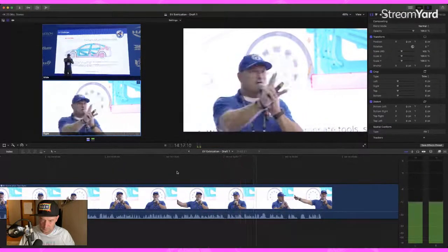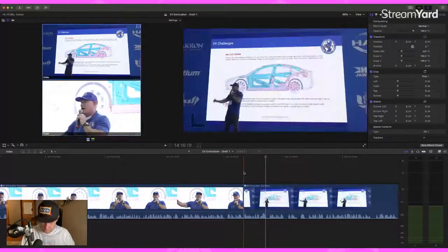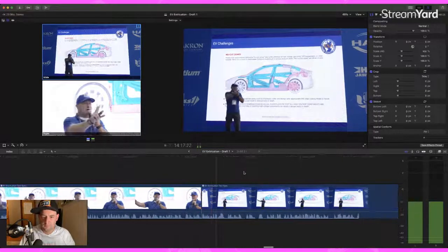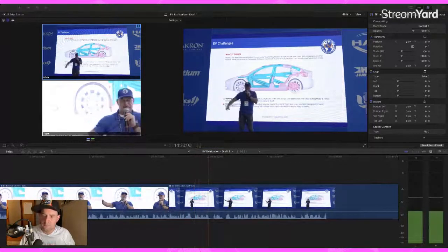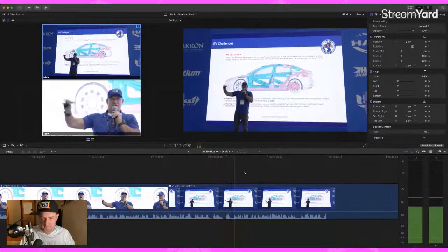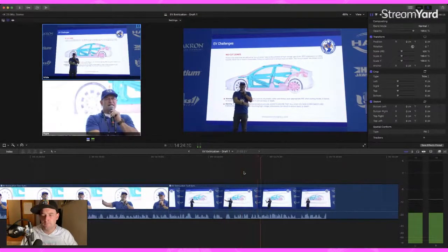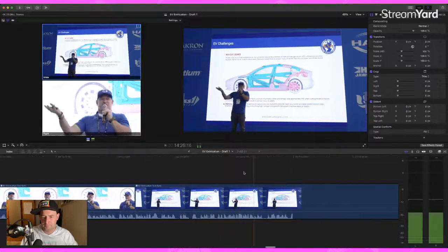All right, I'm going to give you 3 takeaway key moves on the extrication side. A-pillars, all right? We've skinned out the fender. We've busted the hinges on the front door. We're getting ready to do a dash displacement.